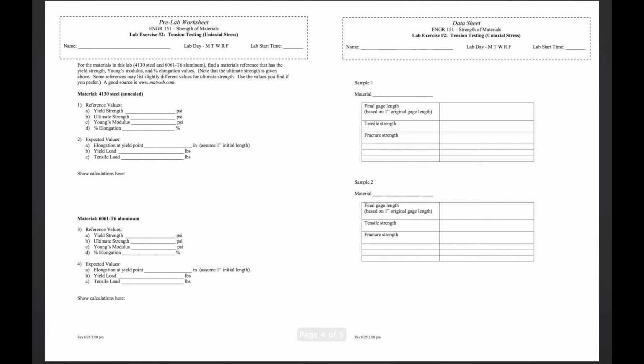Using Excel, generate 2 separate stress-strain graphs for each sample. Using the data from the extensometer, show the linear portion of the curve to just after the yield point. On the graph, label important regions, areas, and/or points on the plot that correspond to the data that was calculated. Remember to include the appropriate title, axis label, and unit of information on graphs.